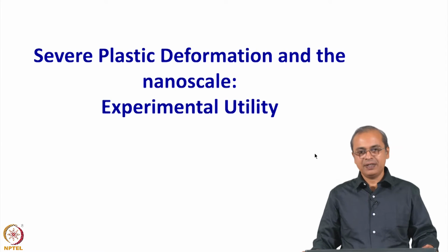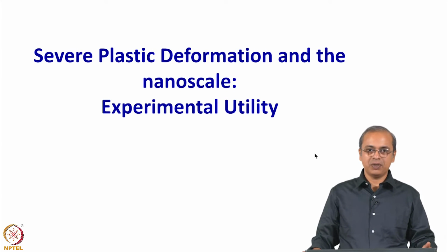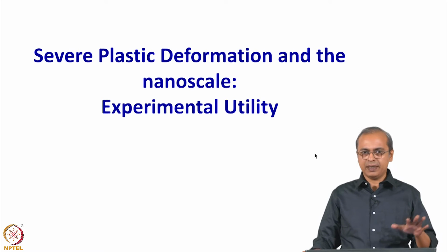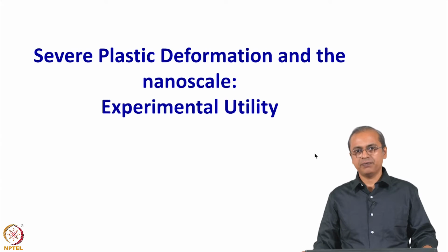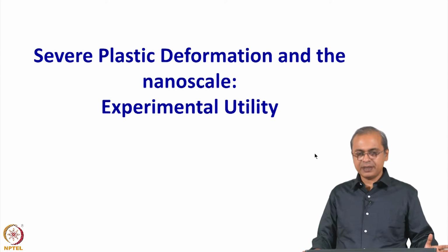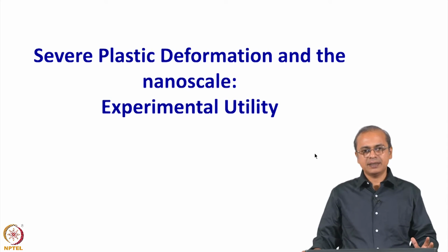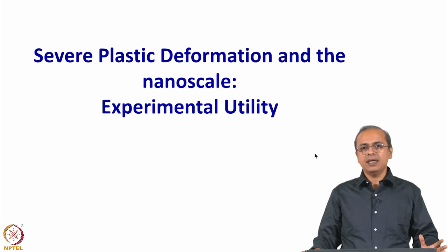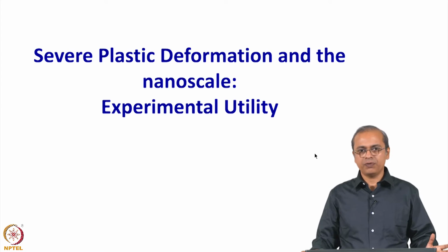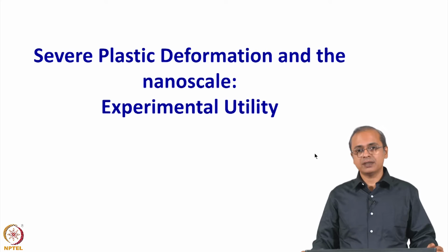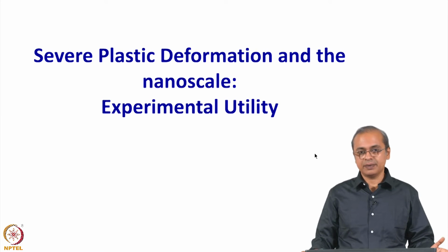Hello, we will continue our discussion on severe plastic deformation. In particular, we are looking at this whole discussion from the perspective of utility in the nanoscale, and severe plastic deformation is a technique which creates a significant amount of strain inside the material and creates a whole lot of equiaxed small grains, several hundred nanometers across, maybe even less than that in size.